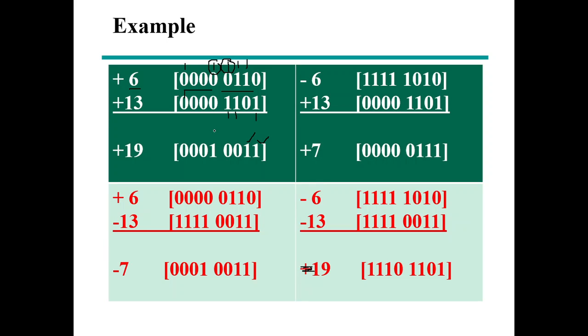1 plus 0 plus 0, this is 1. And all the rest are all zeros. So this is the sum. If you look, the two numbers, addend and augend, their most significant bits or sign bits were 0, and the sum's sign bit is also 0. They're all the same, so there is no overflow. The result that we have is good enough.